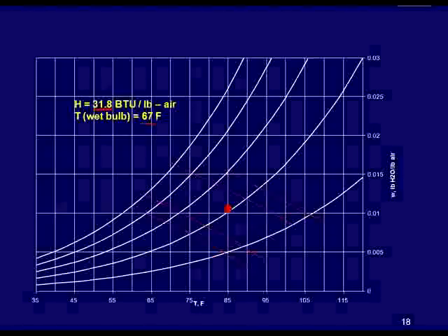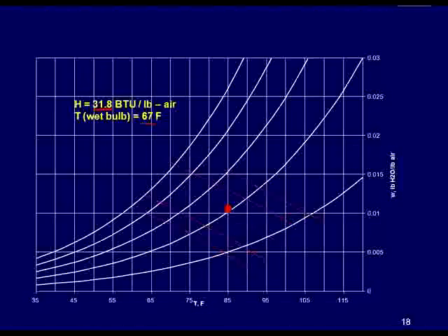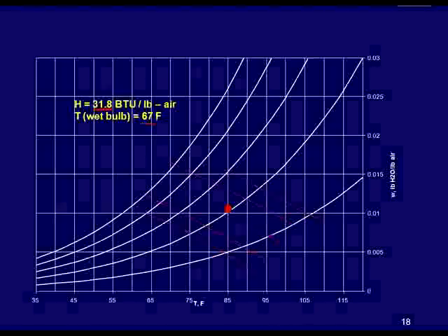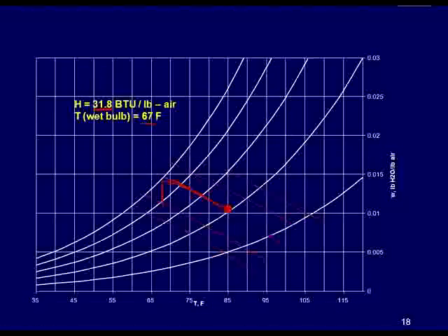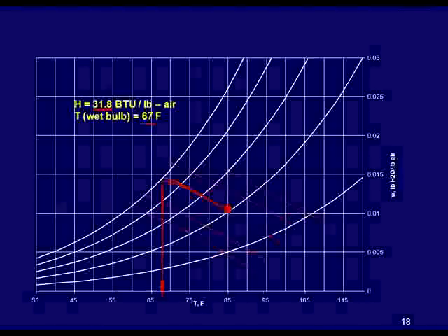So this tells you something, and this is used in dry climates quite a lot. If our humidity was 40%, and often in a dry climate you can have drier air, you can have even very dry air down to 20%. If you take that air at 85 degrees and it's 40% relative humidity, and you follow the dew point line, which is approximately parallel to the enthalpy line, as you cool it, you'll get the wet bulb temperature, or in our case, right about here, 67, 68, something like that, pretty close to 67 degrees Fahrenheit.